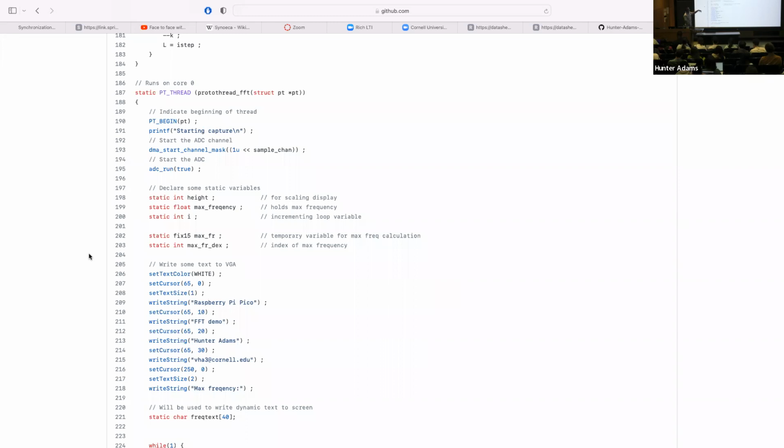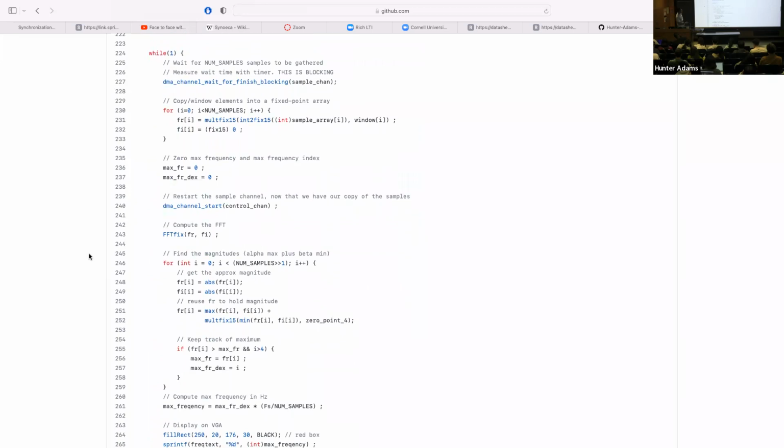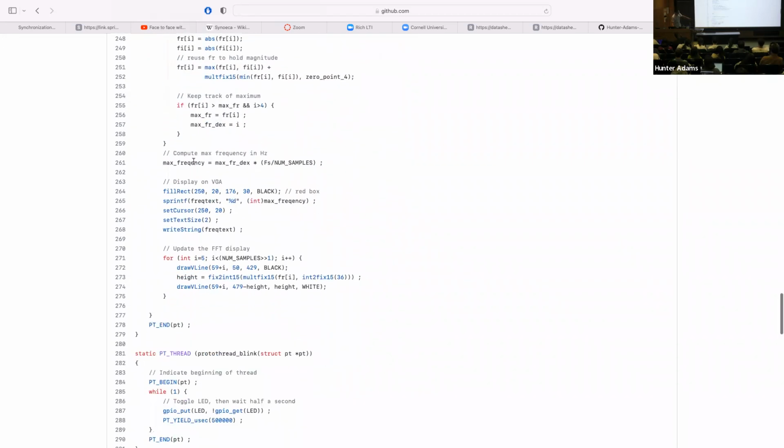setting up and configuring a timer interrupt on core 0 that synthesizes cricket chirps, doing the same on core 1 that sets up and synthesizes cricket chirps, and then having a thread that runs on either core. Suppose you just run it on core 0, because that's what the example does. What this thread will then do is gather a batch of ADC samples, compute an FFT on that gathered batch of ADC samples, and once it has computed that FFT, it will look for the frequency with max power, and it will ask, is the frequency with max power the one associated with crickets?